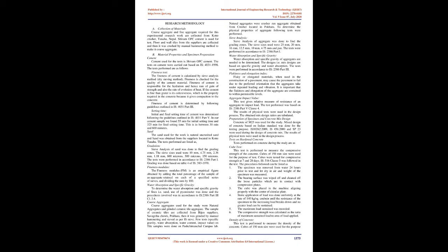Limitations. Some limitations of this study are listed below. 1. Chemical tests were not performed for any of the concrete materials, i.e. cement, sand, aggregate, and water. 2. There are many brands of cement available in the local market, but this study considers a single brand of ordinary Portland cement, Shivam cement. 3. Tap water, i.e. potable water, was used for concrete mix as well as curing, with no consideration of pH value. 4. Water temperature was not maintained at 27 plus or minus 2 degrees centigrade during curing.